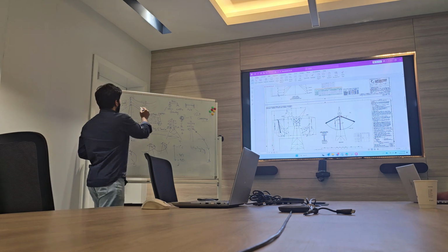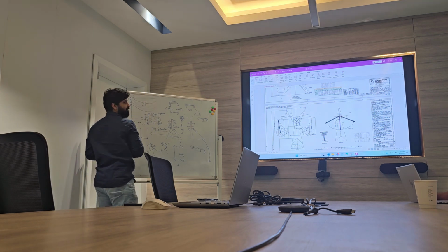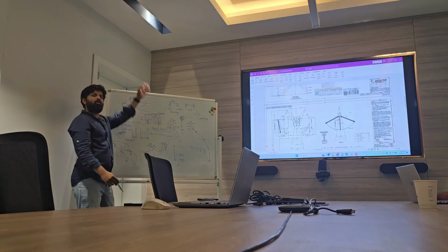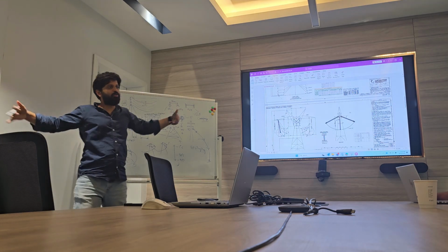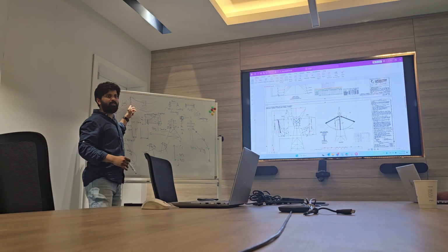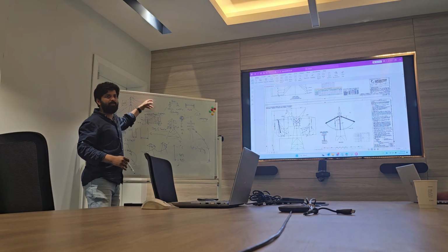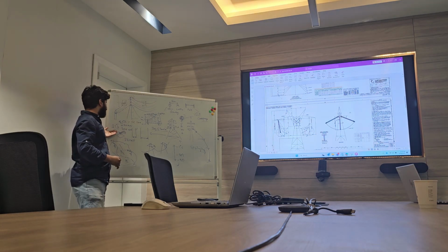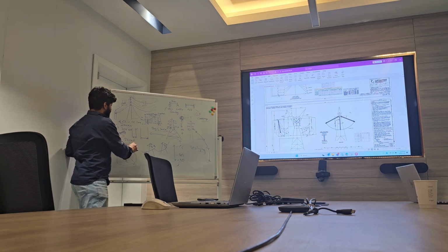If I make it zero, my line will go down. I need higher towers, more right of way, more swing, more things. If I make it tighter, my line will go up, with heavier towers. In both cases, I have a problem. I cannot go too low, I cannot go too high. The standard adopted design tension for this is 21%, and for this is 80%.